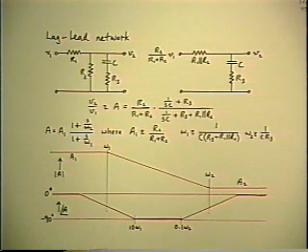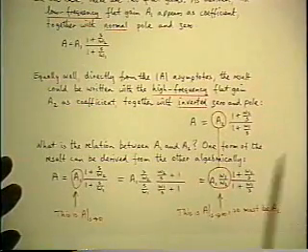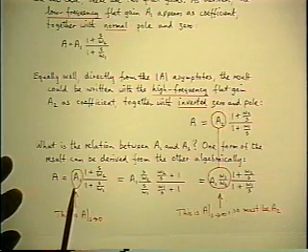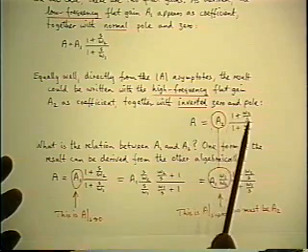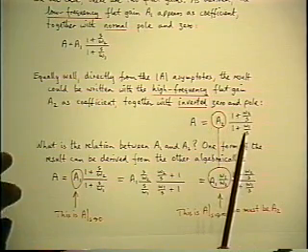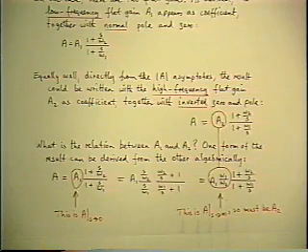And you notice that we now have a choice as to how we represent the function which has that particular graph. We can either represent it with the A1 as the coefficient in front and a normal pole and 0, or we can represent it with the A2 coefficient in front and an inverted pole and 0. They're both the same, they're both correct, and again, it's simply a matter of emphasizing you have the choice, and you use whichever one is most appropriate for the particular application, which means you choose whichever one exposes the gain